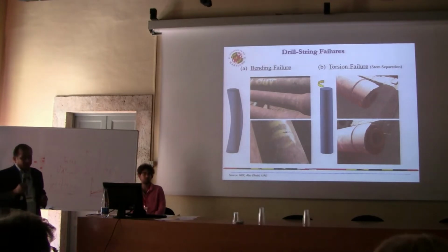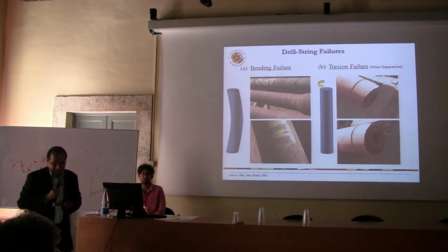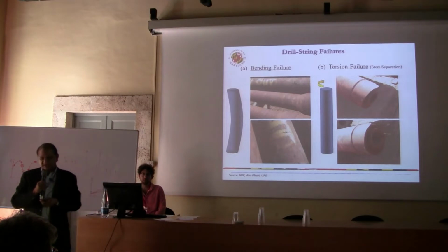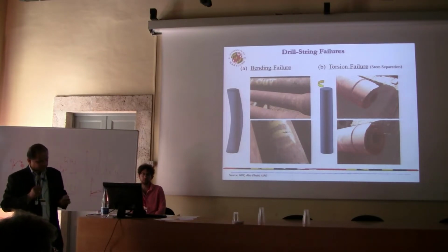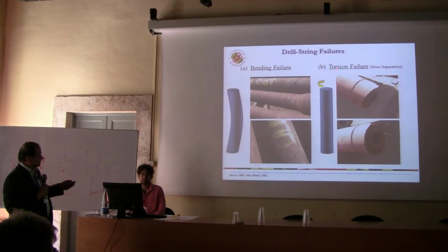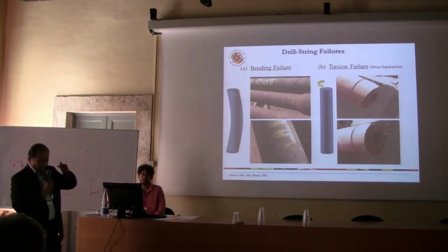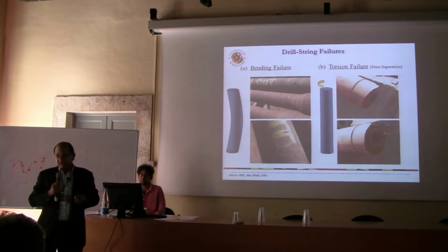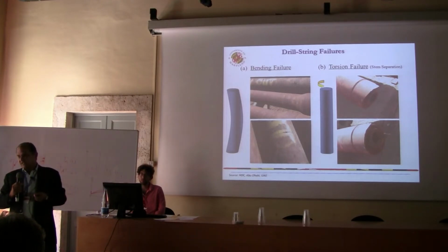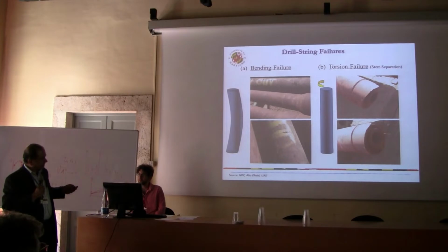One of the starting points when we were talking to the Abu Dhabi National Oil Company is they took us to the National Drilling Company in Abu Dhabi to show us these 2 failures. So this one out here is what is called a washout failure, where purely due to bending motions you develop cracks in your drill pipes, and that leads to failure of the drill string. In the second case, this is a torsional failure when you have the two drill pipes meeting at one location. In between you could have torsional strains that kind of overwhelm the system, and things could come apart as well.